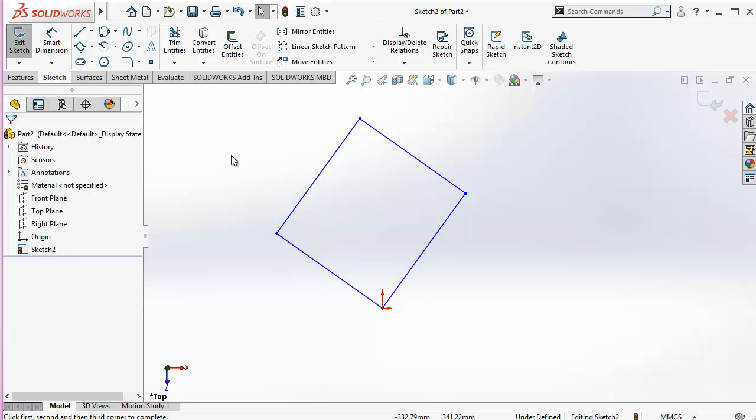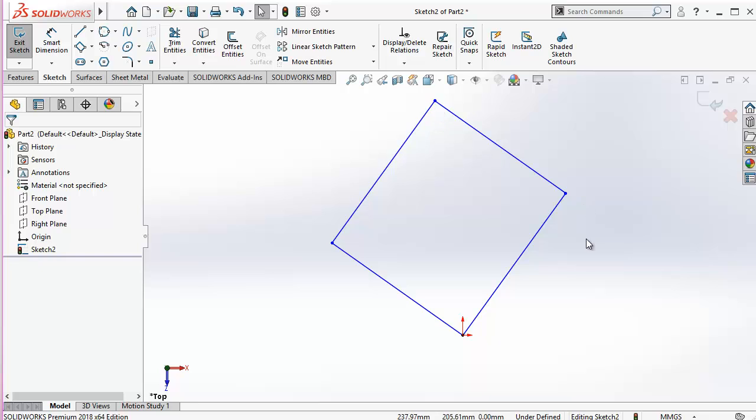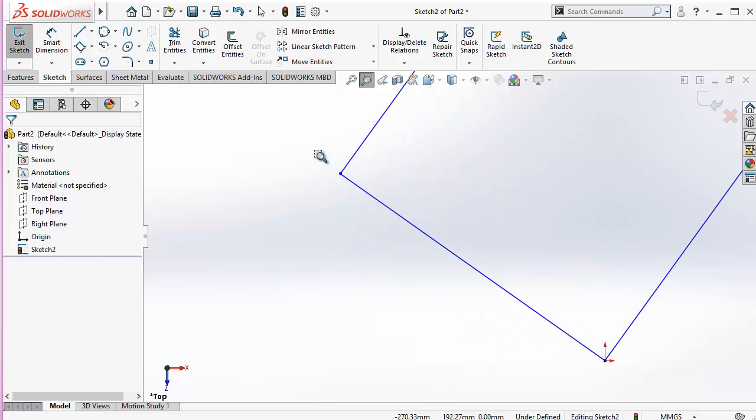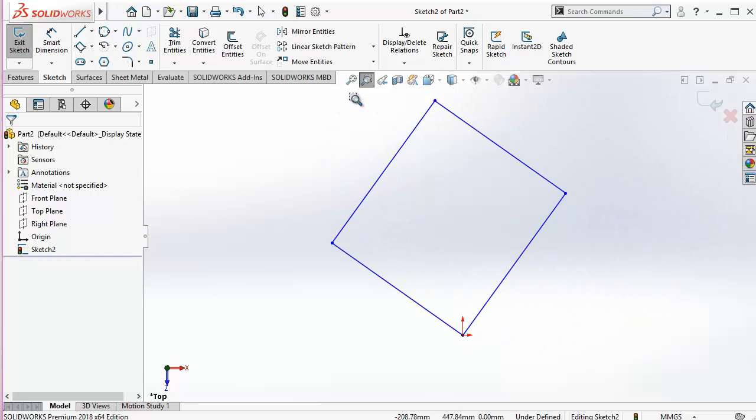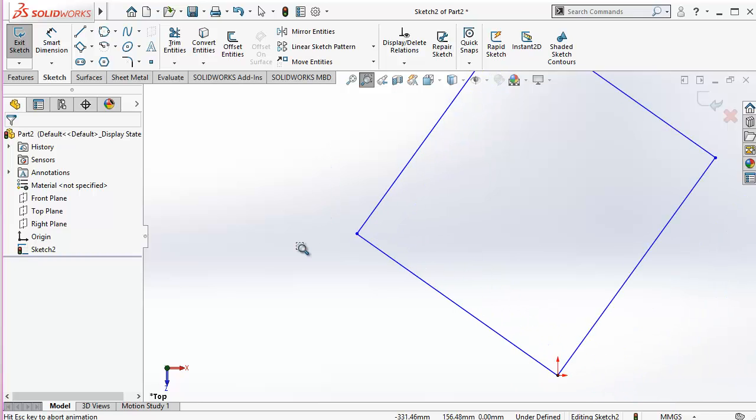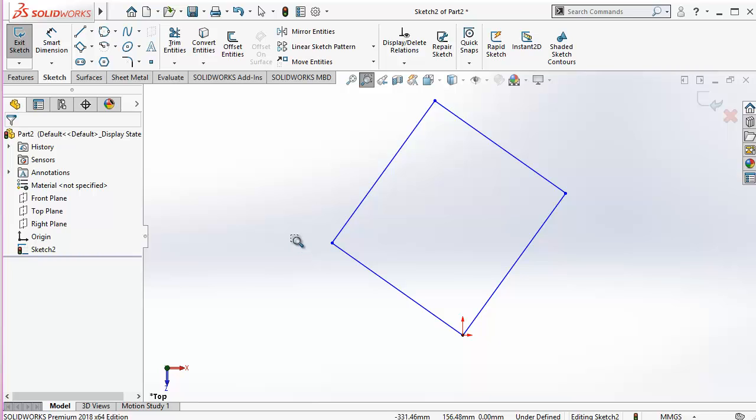Now going further, I should tell you about the use of the mouse as well, how we can use the mouse to place this sketch or the model, which we will be developing later on, anywhere on the screen, and to zoom in or zoom out the model. Going here, this option is for zoom to fit. Clicking on it, you can see it is in its best viewing position, and this one can be used to zoom an area. For example, I want to zoom this much part, so it will be zooming in this much part. Again, we can either use F or click on this one. For example, I am pressing F from my keyboard, and it is now in its best viewing position.